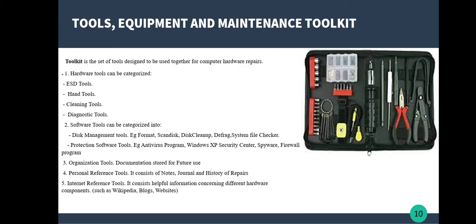For example, you can run the computer, but the power supply cannot function well. So in order to know what's wrong in your computer, you have to use a diagnostic tool, and a common example of a diagnostic tool is a digital multimeter. A digital multimeter is a device used to detect the presence of current and voltage in your power supply system. So when you use a tool like a digital multimeter, you are able to realize what the problem behind your power supply system is.